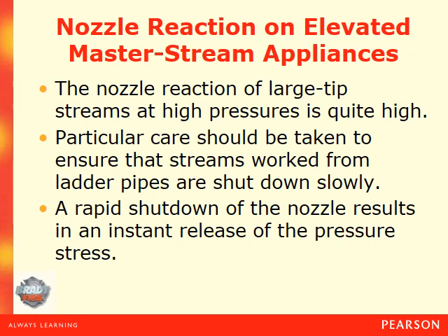So let's look at now the nozzle reaction on elevated master stream appliances. The nozzle reaction of large tip streams at higher pressure is quite high. Particular care should be taken to ensure that the stream works from the ladder pipe are shut down slowly, because if not, then you have that water hammer that we talked about earlier that can cause damage to, of course, the fire hose, the coupling, the pump, and the municipal water system as a whole.